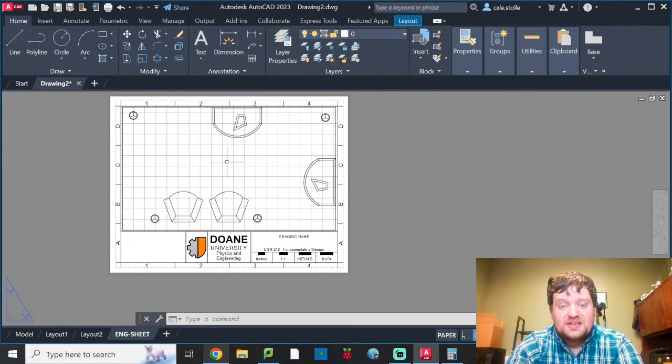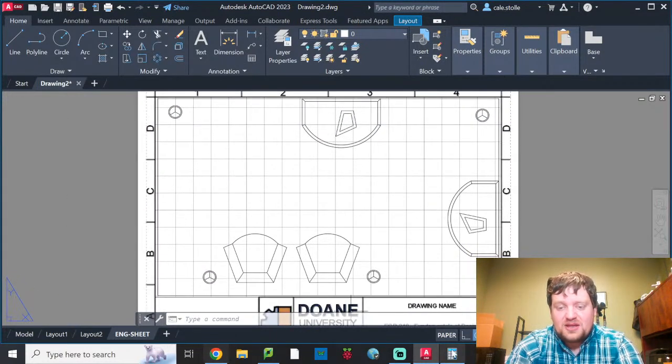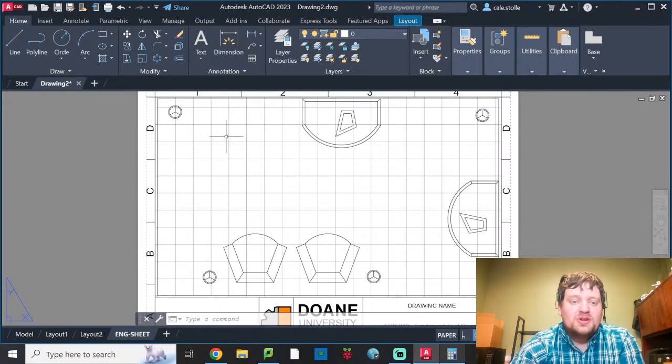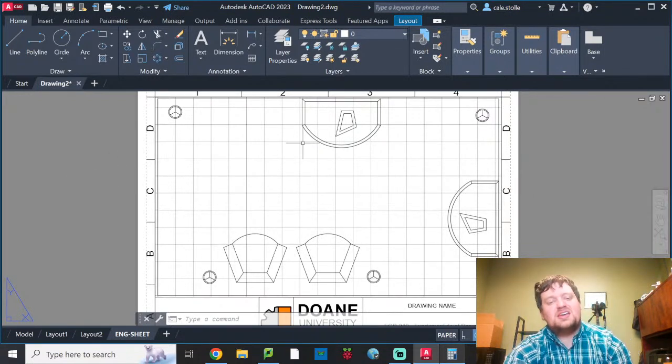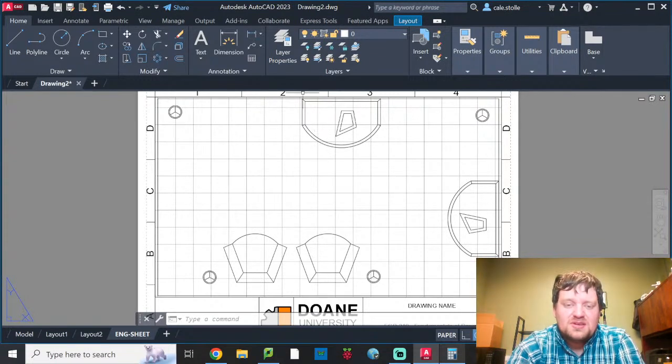We're going to be adding a scale to this. So the first thing we need to figure out is, I've got this up, I've got my calculator up. I would like this 20 by 12 room to take up only about 4 inches wide on this page. Okay, this page here is an 11 inch long page. It's got half inch margins, quarter inch there, quarter inch there, quarter inch there, quarter inch there. So it's really only a 10-inch page. If I have 4 of those 10 inches covered by this, that would be nice. I could go, I guess, with 6.